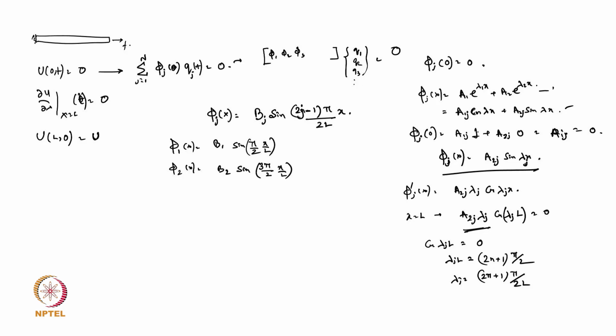For example, you make some structure, then next day your client tells you, no, you should not do it with the fixed, you should do it with the free and fixed. Then again you would have to change the element and all those things, or you run it and your full result becomes nonsense. You don't need to think about that, because there the element does not depend on the boundary conditions, it is free from the boundary conditions. But here the element is dependent on the boundary condition, and therefore your solutions are also much more rigorous and much better, because there you are solving a general thing, and here you are tailor-made for every particular problem.